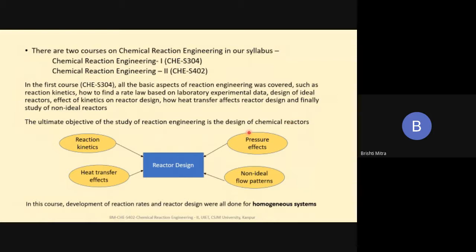And if concentration gets affected, since my rate expression, say for example for a first order reaction, is minus rA equal to k into CA, if CA gets affected, that definitely will have an effect on my reactor design. However, in the case of liquid phase reactions, these pressure effects are not very important because liquids are mostly or usually incompressible, as we call it.